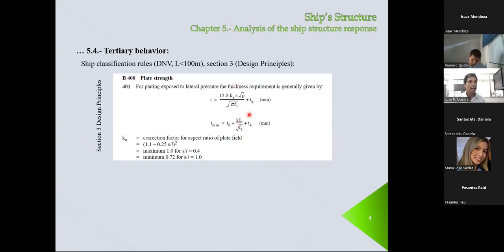But you cannot allow this thickness to reduce more. What do you have to do? Change the plate and go back to the original thickness. Because if you reduce the thickness more than this, that represents a hazard. If you apply the P, the stress will be above the allowable value, and you cannot allow that in your structure.